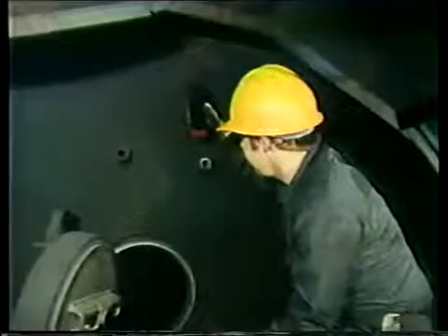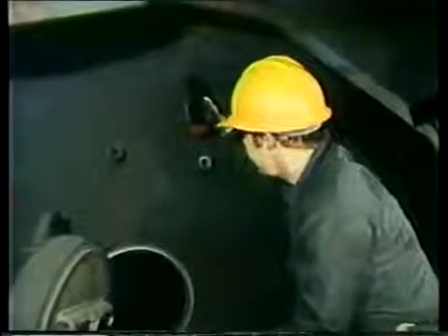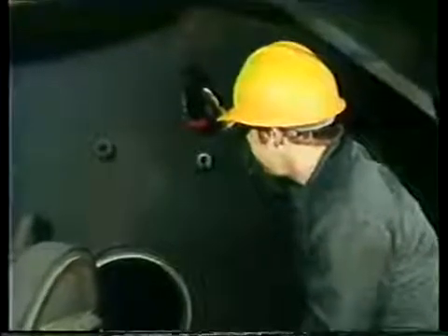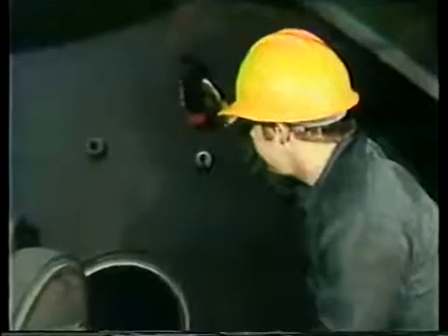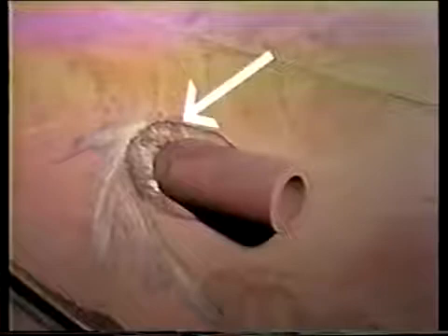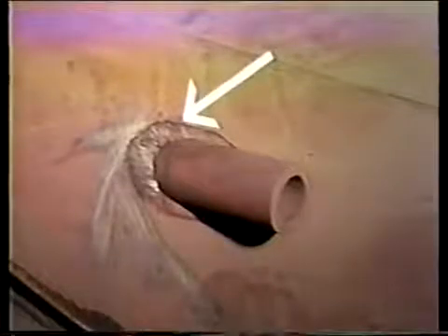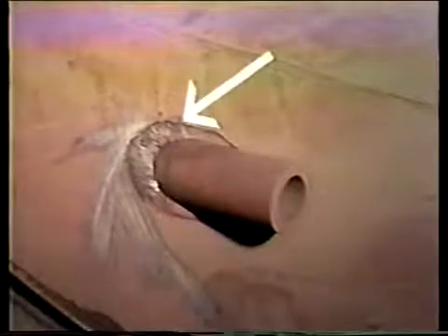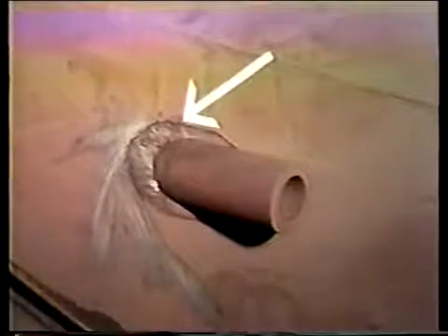Nozzles must not be plugged with sludge or scale. Pay attention to nozzles that would be underwater during normal operation. These are most likely to become plugged. Also check the welds that attach the nozzle to the vessel. The welds could have cracks, as well as evidence of corrosion or erosion.